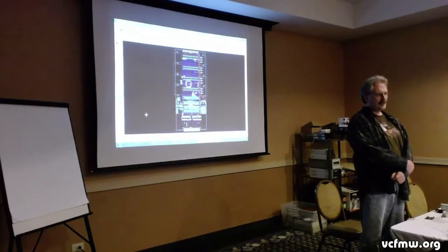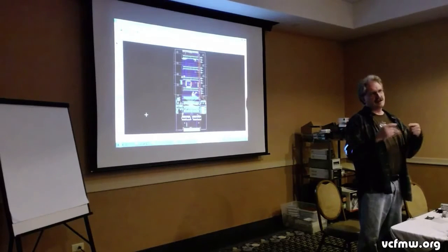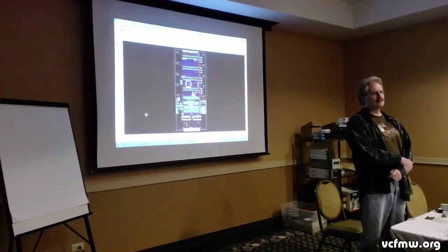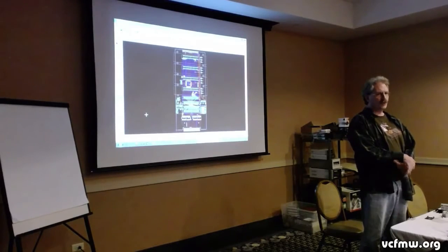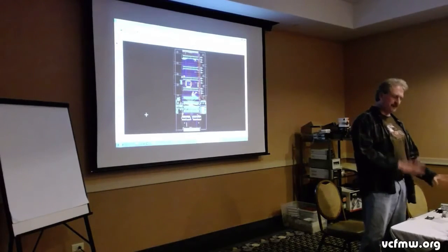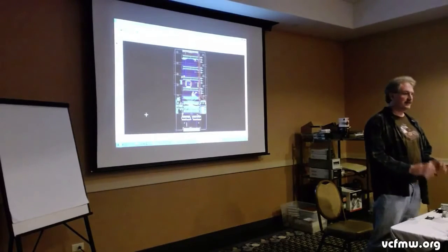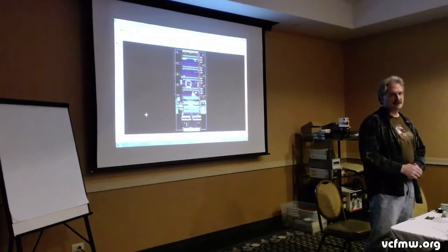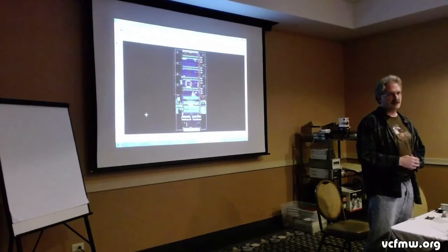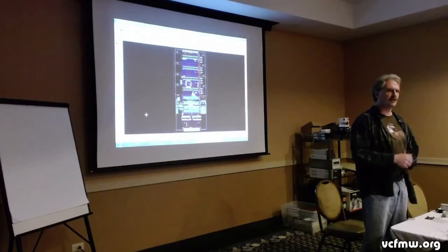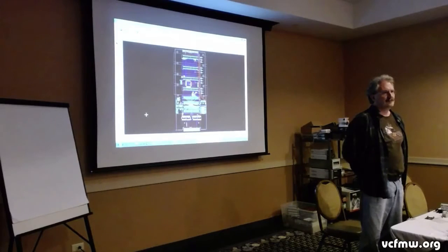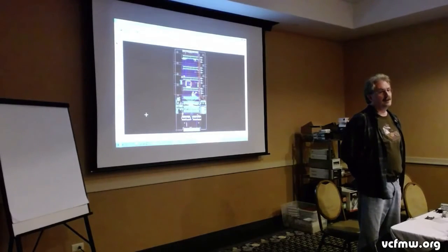The problem with dual rail buffers, I think, is they're not bi-directional, right? They usually go one direction and then the other direction for the drive. So you do have to do some work when you're buffering with the outside world. Luckily with CPLD, that's the reason I think CPLDs are nice, because at least in this space, you can get by without having to do a lot of complex buffering. Getting into the FPGA space, you definitely have to do something to connect yourself to the outside world. And TI makes the dual voltage buffers as well.